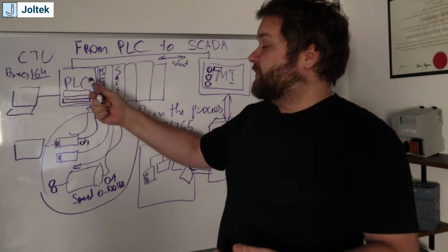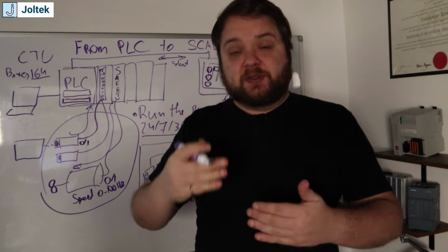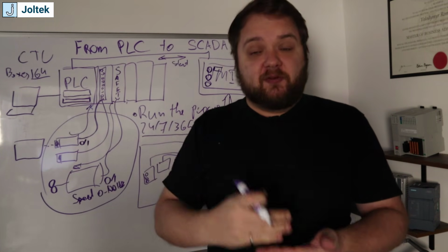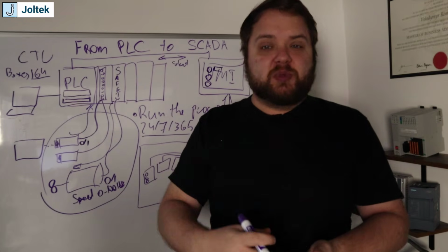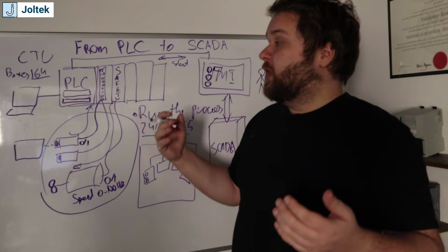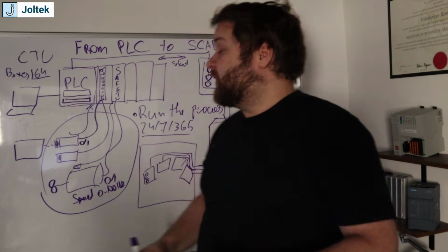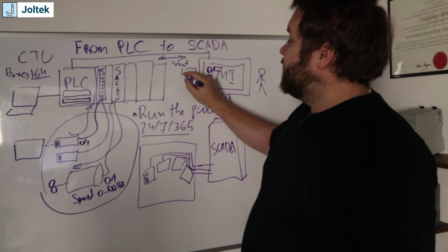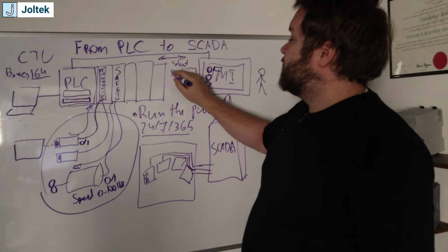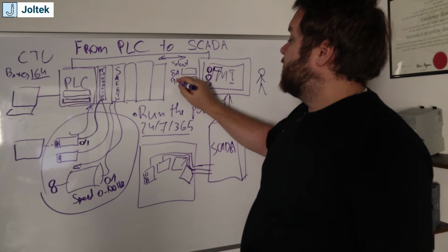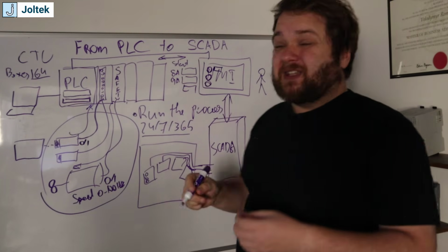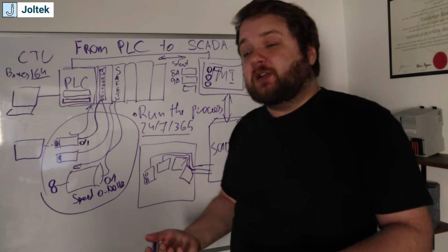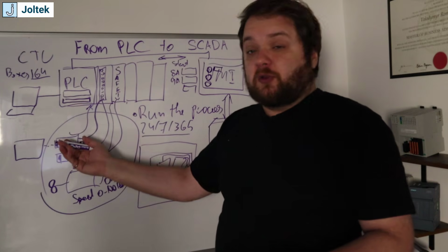right? So your PLC is going to have a register for time. And so from 8 a.m. to 9 a.m., it's going to count 164 boxes. From 9 a.m. to 10 a.m., for example, it's going to count 74, so on and so forth. So your HMI can also have a set of registers that will display that information, right? So here, 8 a.m., 9 a.m., so on and so forth, so that the operator can understand the data beyond just knowing when the sensor turned on or off.